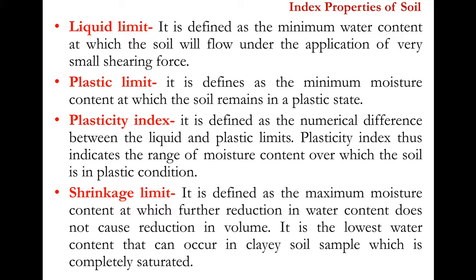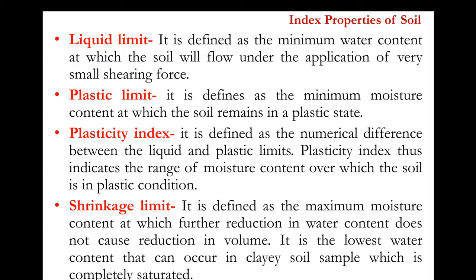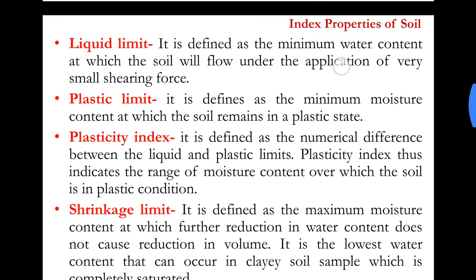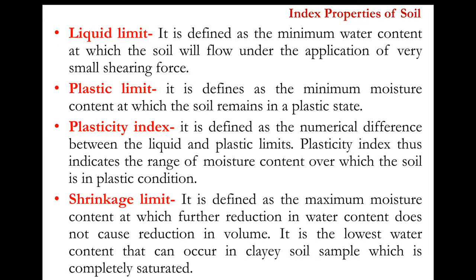Now what is liquid limit? It is defined as the minimum water content at which the soil will flow under the application of very small shearing force. So it is the minimum water content present in the soil sample, due to which the soil will act like a liquid and it will flow under the application of very small shearing force.